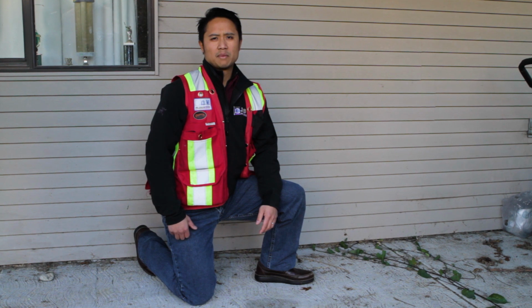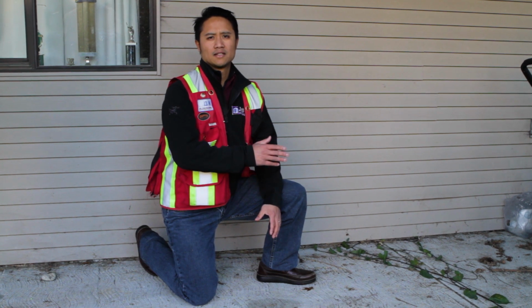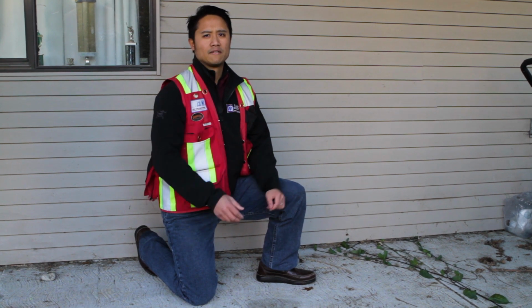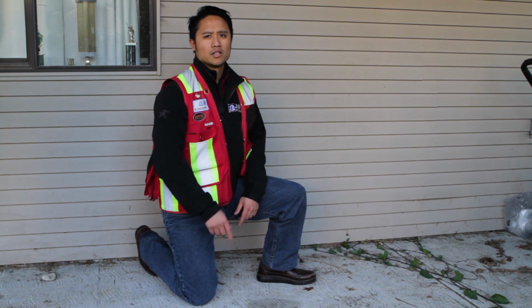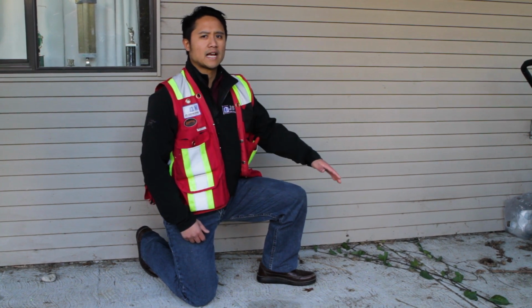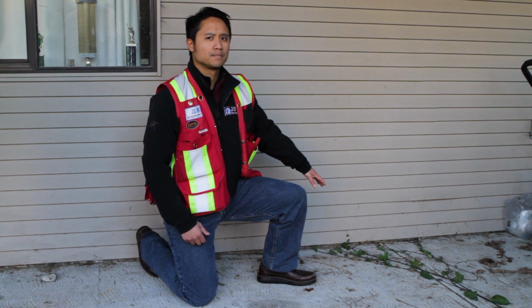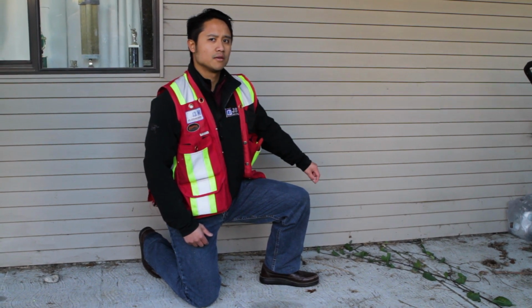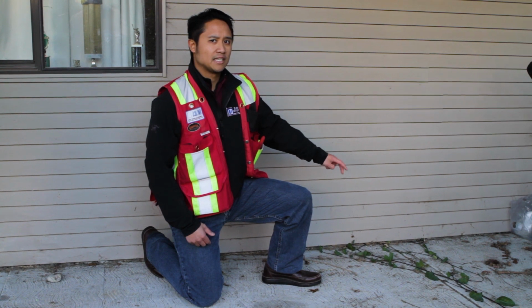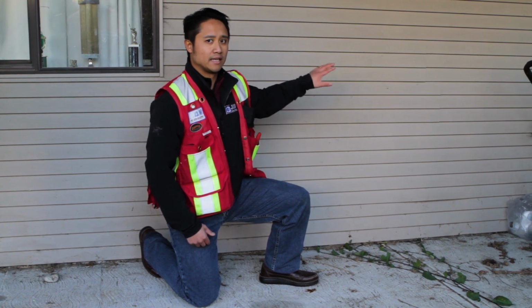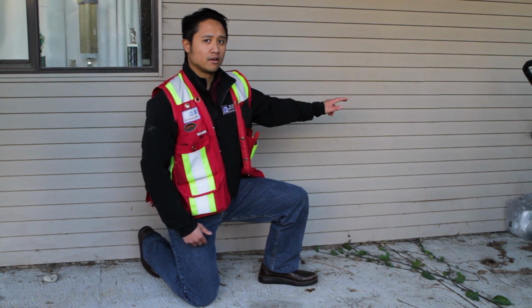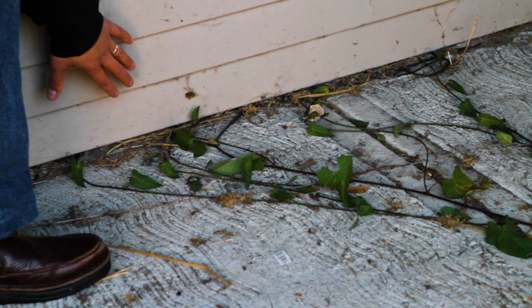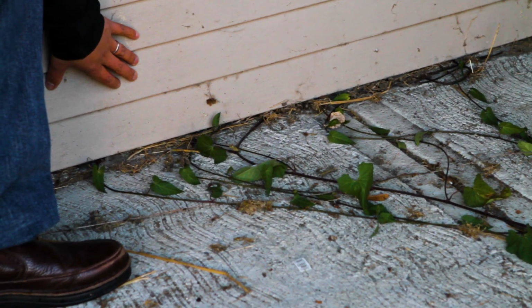One of the important things about reviewing a house like this is seeing how the landscaping affects the building envelope. So in this case, what we see is some vine that's actually penetrating into the building envelope. And that's bad for a few reasons. One is it easily lets water in through the branches and the roots. The second is it actually lets air into the building envelope and into the interior of the building. And third, it lets pests and insects into the building envelope and potentially deteriorate the wood framing.